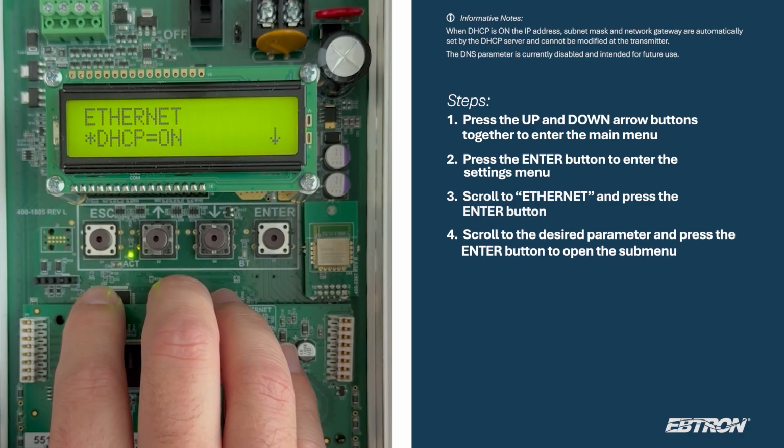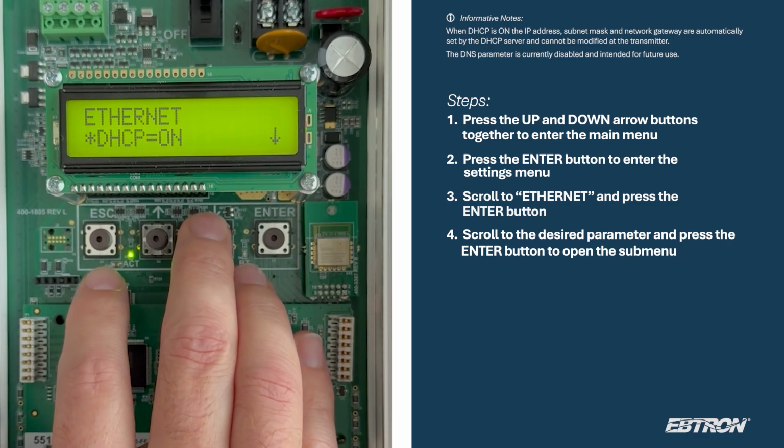The Ethernet menu contains several key parameters that define how your transmitter connects and communicates on the network. Let's walk through each one briefly. Dynamic Host Configuration Protocol. This setting determines whether the transmitter automatically receives its IP address from the network. The default is on. When DHCP is enabled, the IP address, subnet mask, and gateway values are assigned automatically and cannot be modified. If you need to manually configure these network parameters, set DHCP to off.